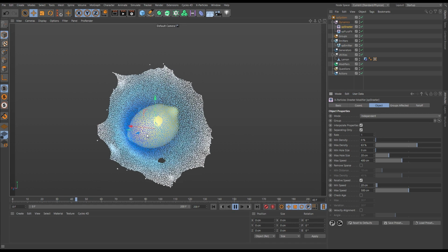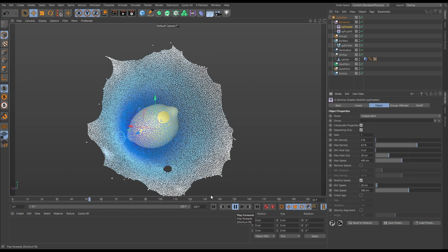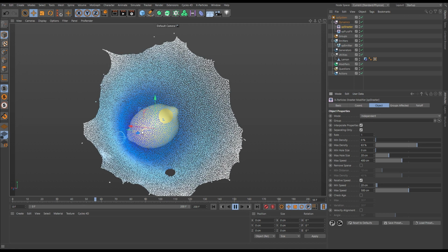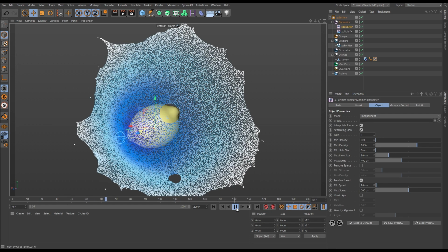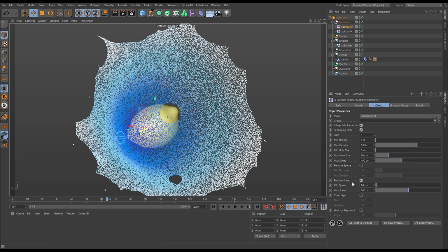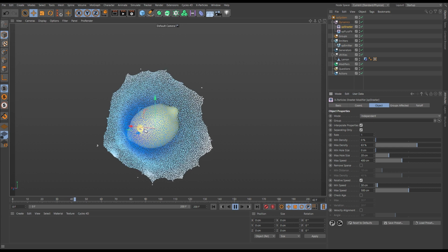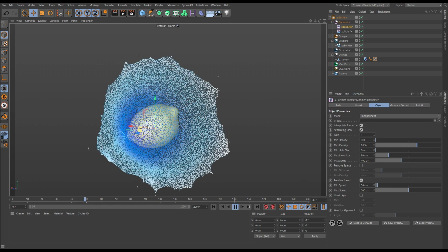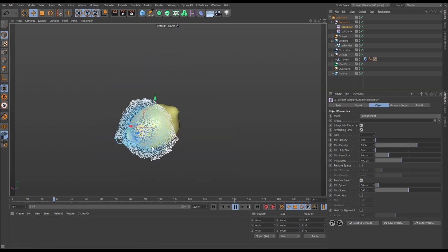Yes, look, we've got a hole here, but still it's too great. We're starting to get a hole here as they're moving more slowly, but they're still moving quickly enough. There are enough particles moving quickly enough to be considered for sheeting. So let's make that an even higher minimum speed. And then we've got a hole developing, but these ones are still moving fast enough to sheet. So let's go up to, say, 50 centimeters. Go again. And there we go.